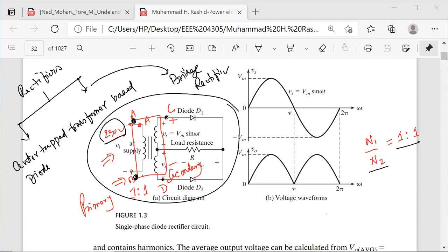Okay, so now yes, the voltage, same voltage 230, but in the middle of the winding, in the center of the secondary winding, suppose this is your primary winding, this is your secondary winding, we take a tapping here. This is known as the center tap. So this is your say half, and this is also half, and suppose this is 1. So then what will be the voltage? If this is your 230 volt, what will be the voltage from here to here? 230 by 2 in each. Yes, that means 115 volt, right? It will be 115 volt.